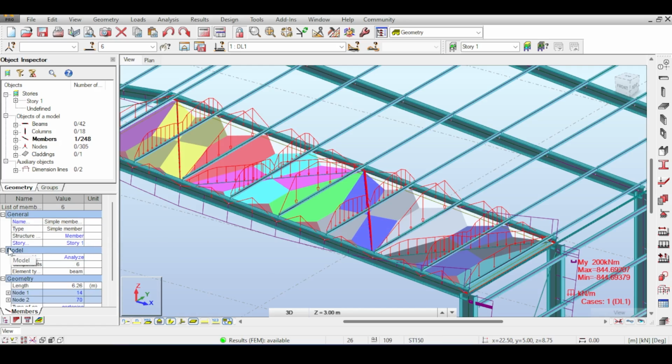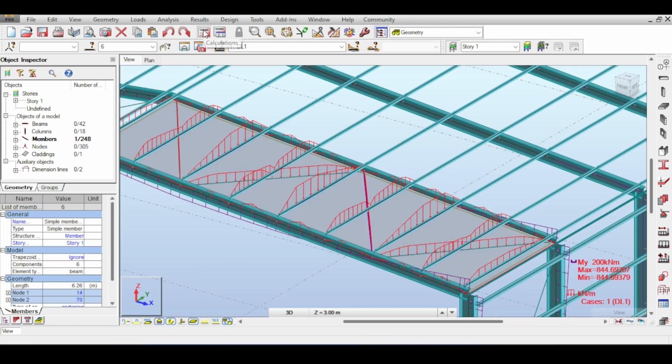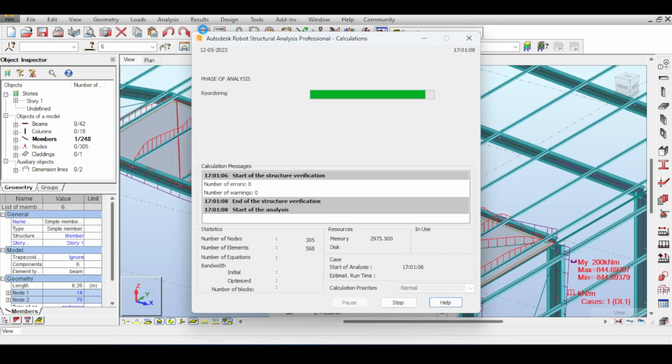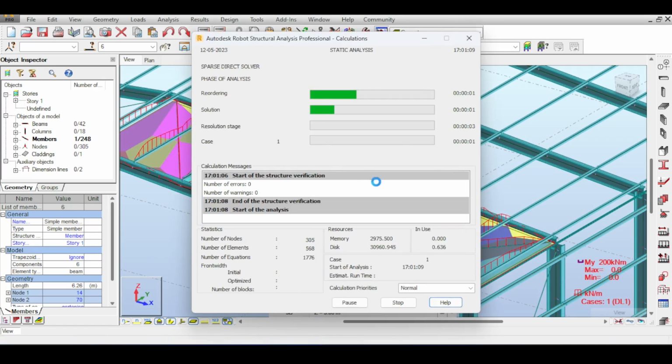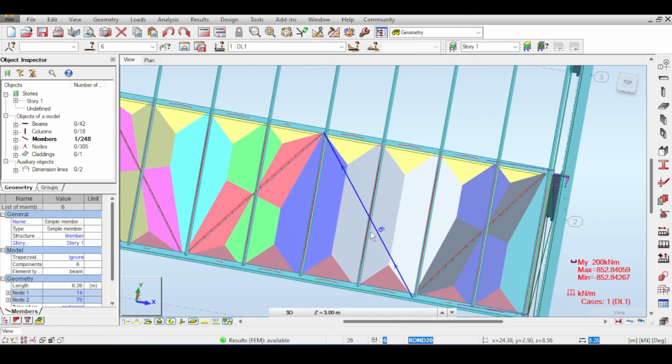If you go down to the model, there is something called trapezoid and triangular method analyze. This means that for the triangular and trapezoidal method, this member is visible and will be analyzed. If you select ignore and run the analysis again, then you have solved only part of your problem, but at least it's one part in the correct way. So if you click on analysis, you can see now that indeed the trapezoids and the triangles totally ignore this element, so this is one problem solved.